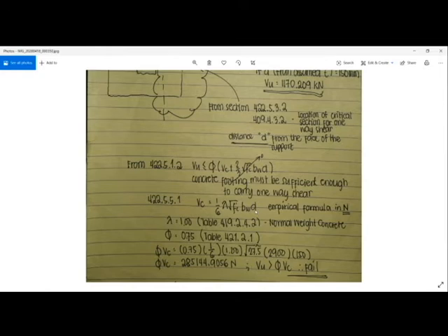So you have to remember na kung Newton yung formula natin, Newton yung kalalabasan na unit dito. So you have to remember na this f'c is in megapascal or Newton per millimeter squared. Yung bw natin is in millimeter, ang depth natin is in millimeter.